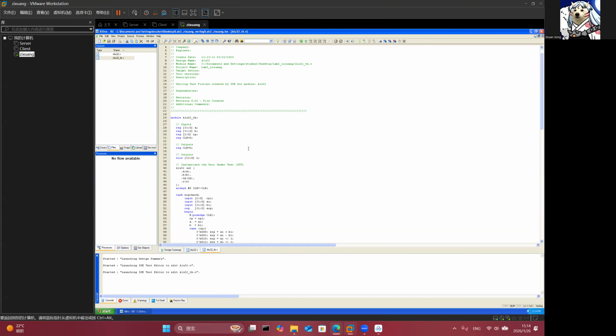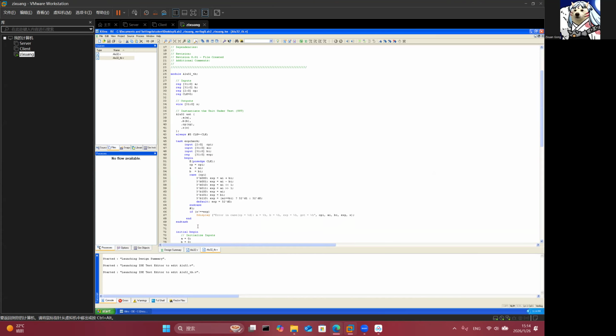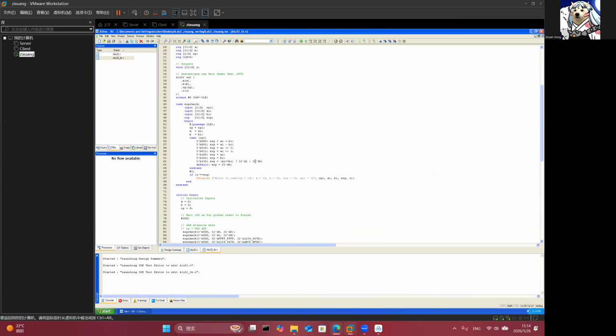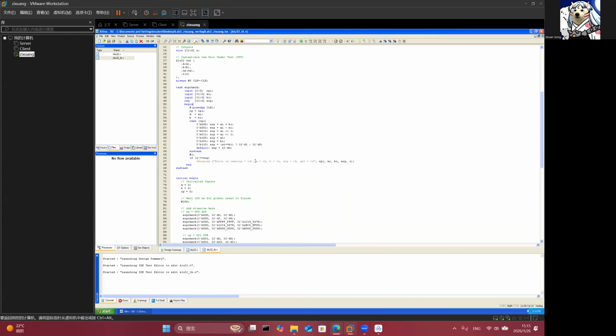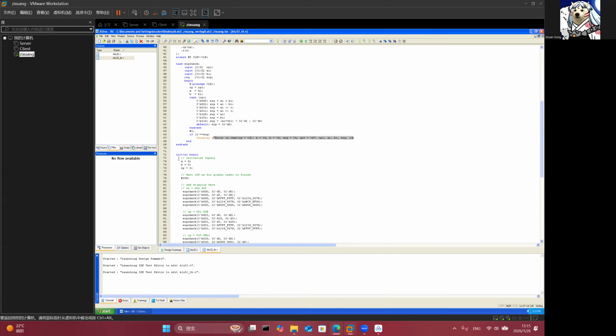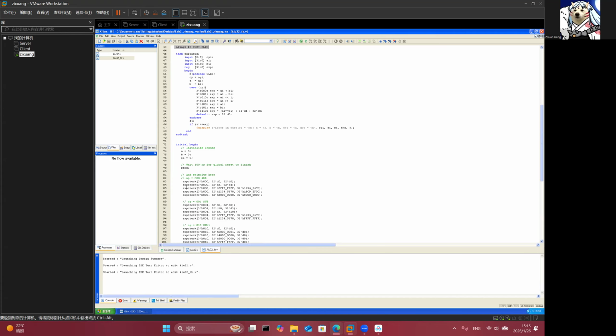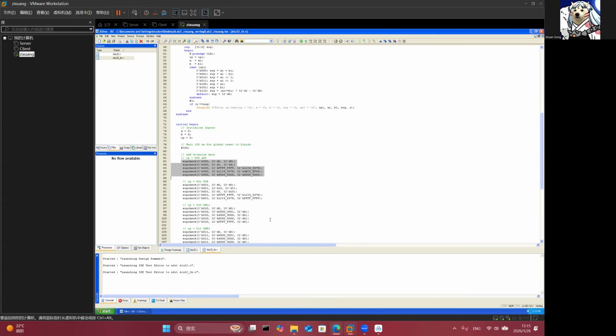So in the test bench, I make an expect check function task to check it as a loop, so I can do the check easily. It's the same functions, and if it's not the same as the expectation, it will display the error. And this is the initial. Also, this is the clock. And then I just write the input and check the result.